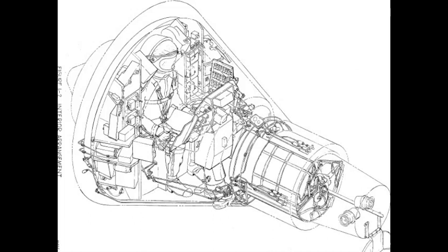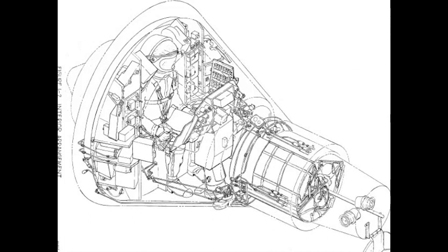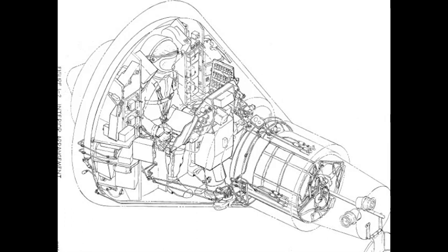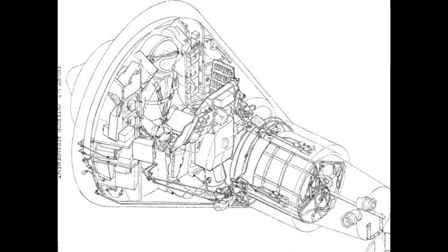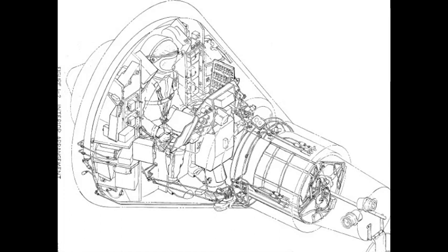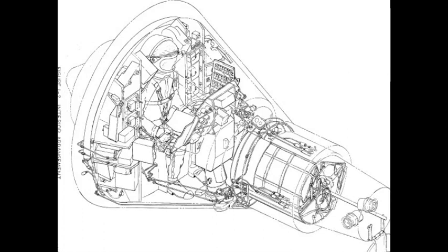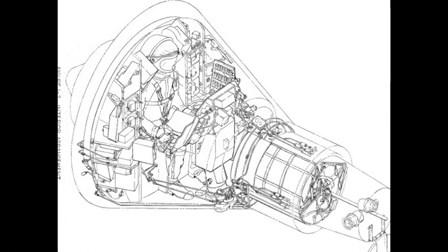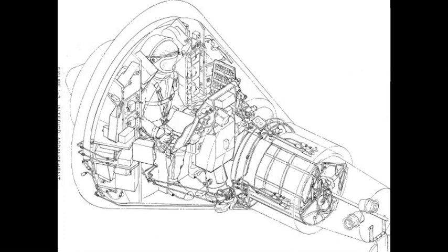The afterbody conical section exterior shingle arrangement extends beyond the large pressure bulkhead to the forebody heat shield and encloses the equipment located between the large pressure bulkhead and the heat shield. Located adjacent to the capsule forebody and afterbody juncture and bolted to the heat shield attach ring is a fiberglass attach ring. During capsule adapter installation, the fiberglass attach ring and the adapter attach flange are clamped together with a segmented clamp ring.